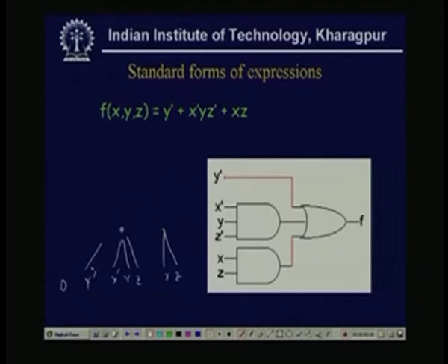See, it is only one literal, so as if it is ANDed with itself. So, 3 ANDs. So, this is my first level. Now, again these 2 OR operations are in the second level. So, this is my hierarchy. Actually the inputs are at the 0th level. So, that means y dash, x dash y z dash, x z, they are at the 0th level literals.